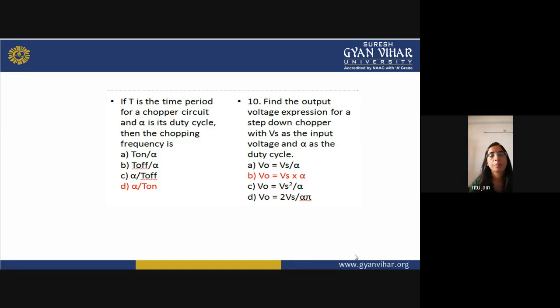And in a buck boost chopper, both operations can be done. It may be step down or step up, and it behaves like a transformer, which works in AC to step up or step down the voltage. So it is identical to a transformer. And all of this depends on the duty cycle of the chopper.